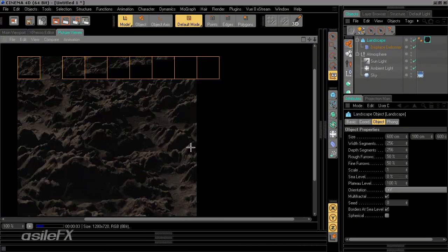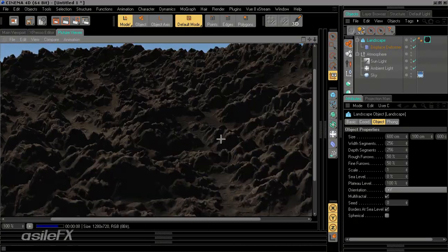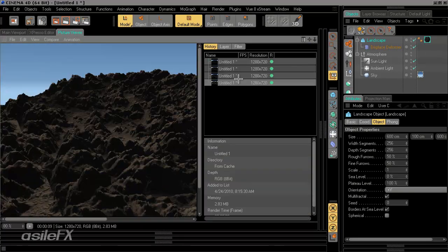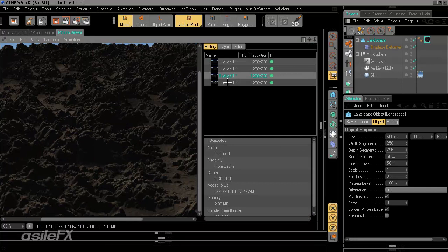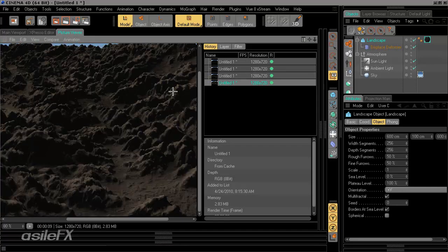Now I do have what's going to end up being a slightly lower displacement quality overall because it didn't quite match up perfectly. And that's because my subdivision level went from 5 down to 2, so I would really need to increase the resolution of the terrain. So if I increase the resolution or increase the sub-polygon displacement, they'll basically end up looking the same.